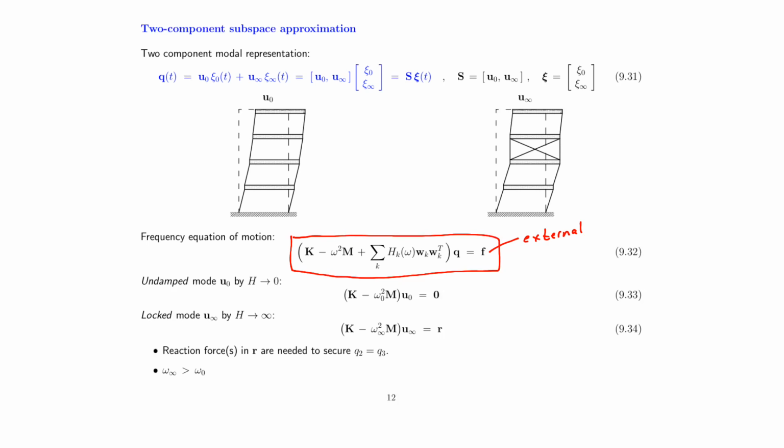Now we want to do system reduction on this equation of motion, because we want to find the optimal transfer function, and of course for our viscous damper we want to find C optimal. And it's just too complicated to have 932 written in the way it is. Now we would like to go to modal analysis, as indicated in 931.